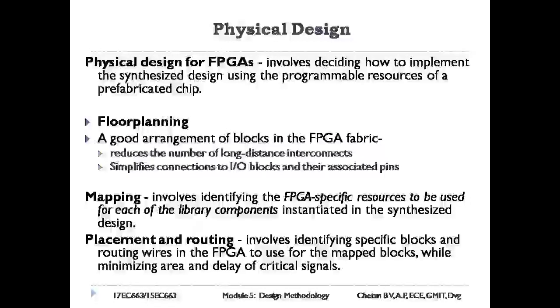For smaller FPGA-based applications, the floor plan generated automatically by the vendor's EDA tools is sufficient. For larger designs, if there is difficulty in fitting a design into a given FPGA, either attempt to improve the floor plan or use a larger FPGA.